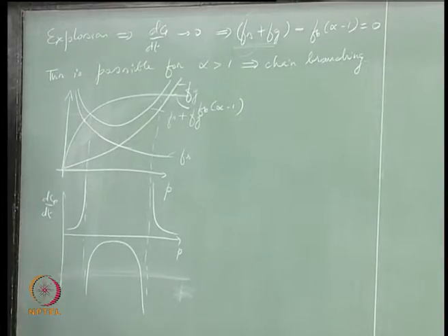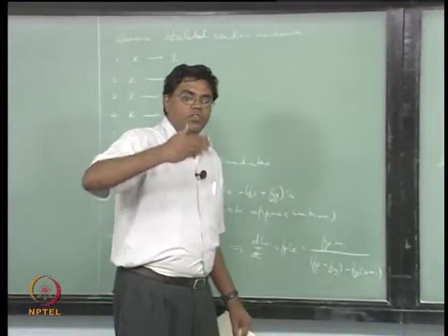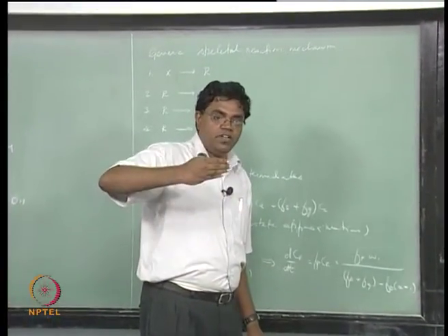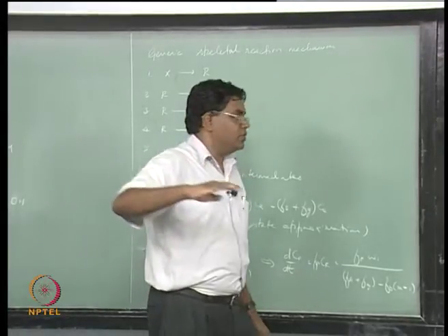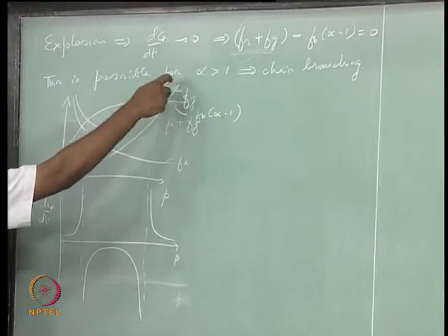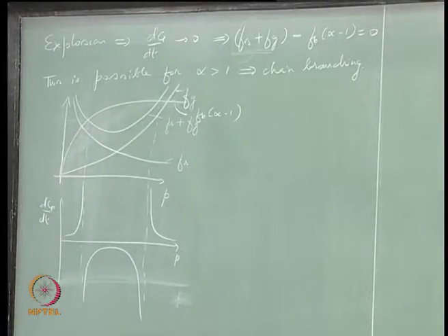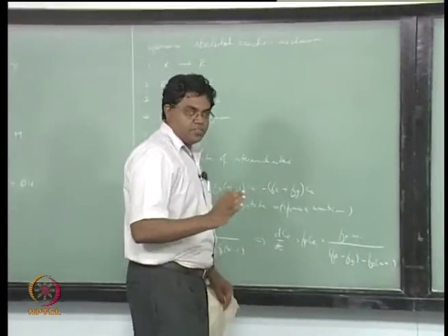That means you now have a lot more gas phase termination, right, and so the gas phase termination keeps increasing, but the production is not increasing that much, okay. So this is now tapering off, and then you have a reversal again of Fs plus Fg exceeding Fb times alpha minus 1. So these two pressures now, we are looking at pressures essentially, right.